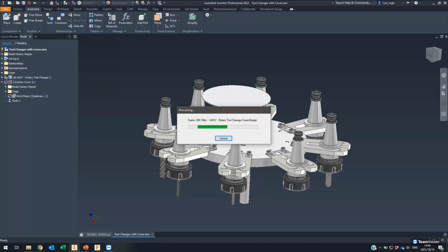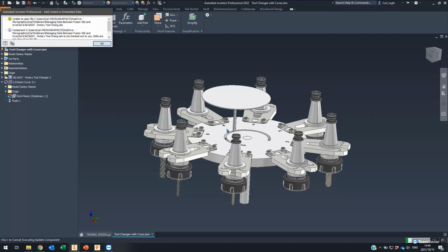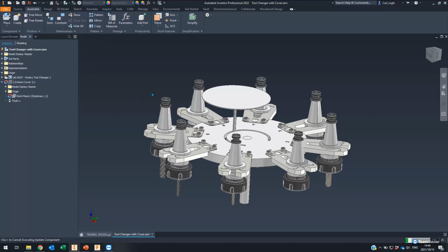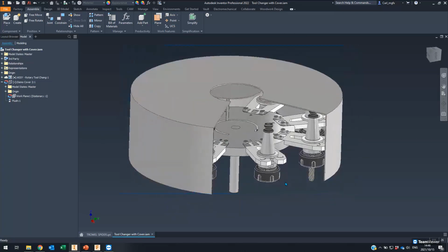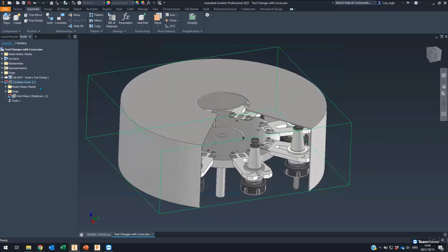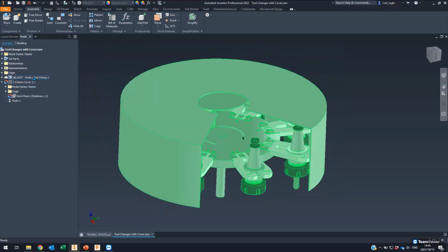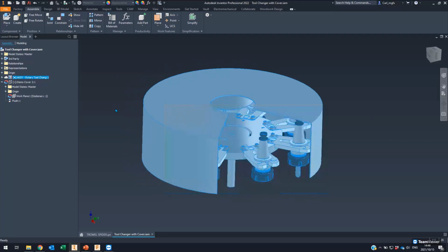So we can actually notice there now a little lightning bolt next to the cloud, and we're pulling the updated design through. So the carousel may have been changed from being an 8 tool system to a 10 tool system, or maybe a 6. And this would basically update accordingly. And then we see our update come through with that part brought back in. You'll see I have switched off the visibility of the old demo cover. That is now part of the import from Fusion.